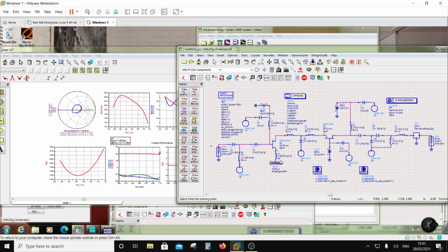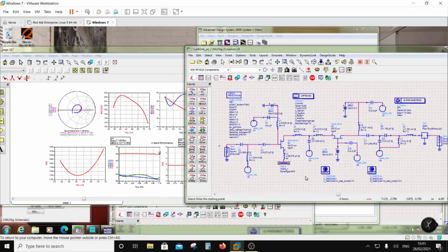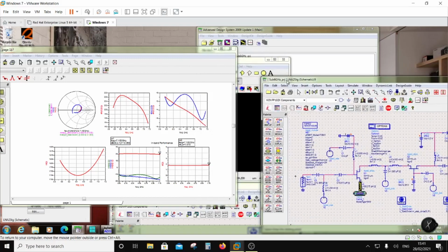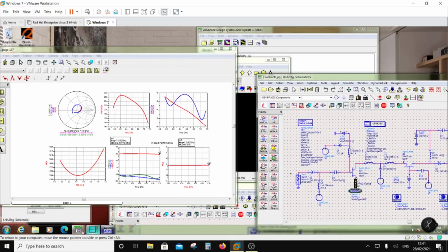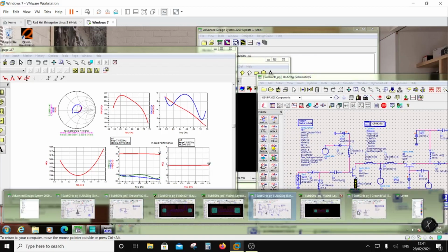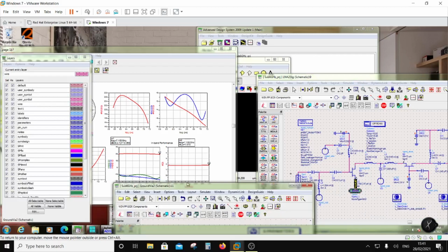One is the via inductance which we simulated in momentum, and then we introduce the additional inductance here of 90 picohenry, and that has to be absorbed into the layout. So what we do is we just copy this section into a separate file and find out what this inductance looks like. So what I have done is I have copied this over here.